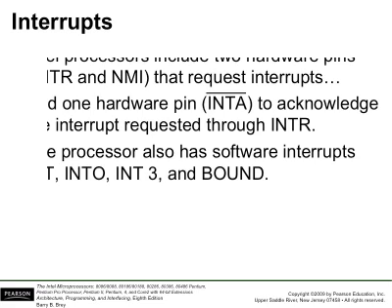Intel's processors can also handle software interrupts whenever your program explicitly executes instructions such as INT, INTO, INT3, and BOUND. These are considered software interrupt instructions. Once your software calls these instructions, the processor will respond similarly to a hardware interrupt. It will stop executing the main program and then handle this software interrupt. Essentially, it's going to execute a special routine that deals with this software interrupt.